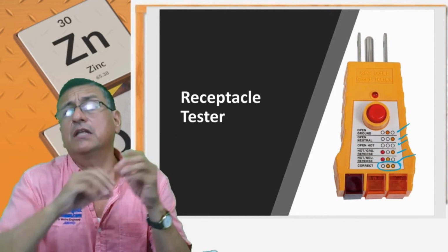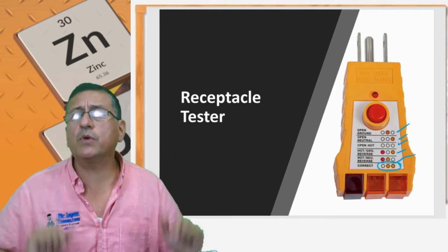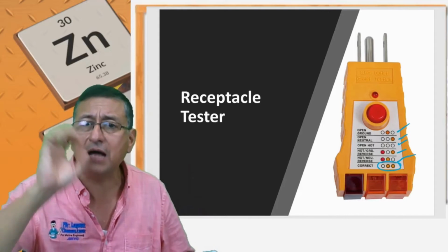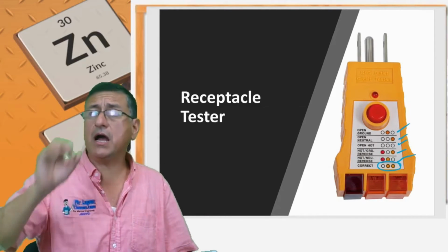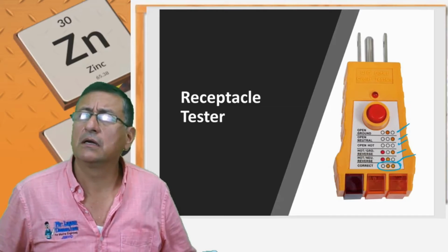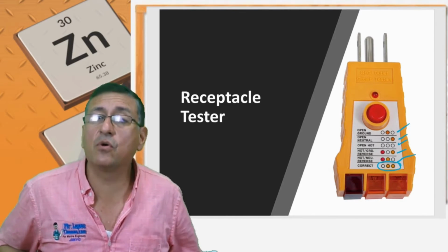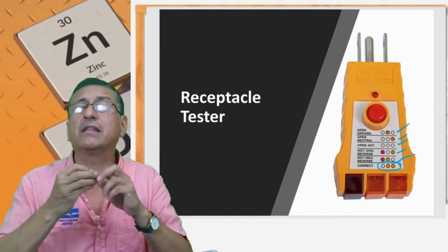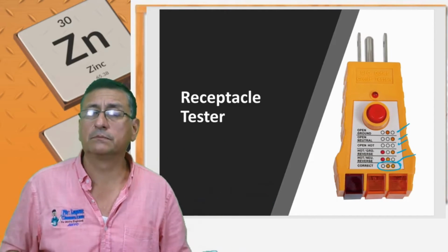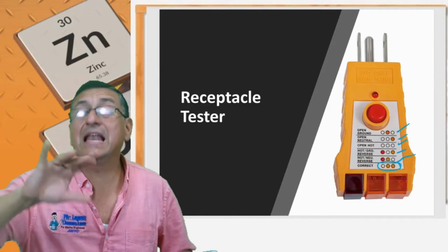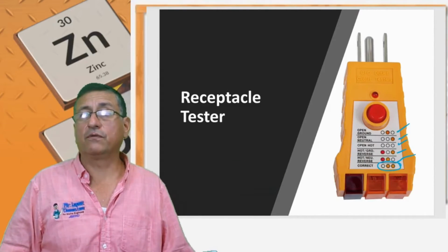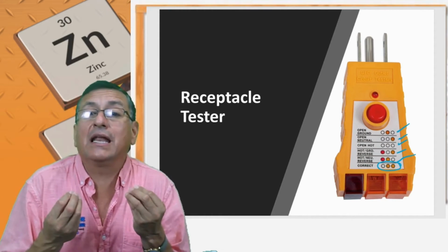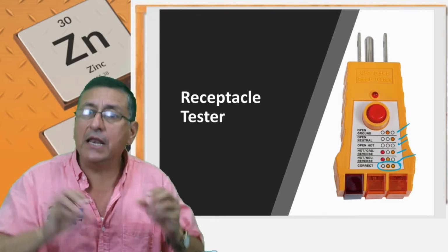Yeah, the bonding is designed to drain current in some situations, but normally through the bonding system you should have 0 amps. If you have 5 amps constantly through the bonding, that excessive constant current accelerates the corrosion between the dissimilar metals in contact with salt water. Simple. We need to eliminate those sources of leaks in my boat, and in the next episode I am going to analyze how to identify where the leak is.